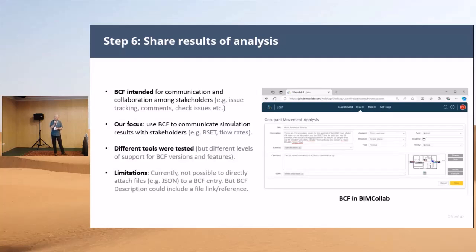We use different tools, and ultimately there were some limitations that we encountered with the BCF file format, primarily because it was originally designed as an issue tracking tool with fairly small notes and packets of data going around the design team. We wanted to associate it with larger sets of results. We wanted to know the flow rates through the doorways, for example, over time, and the performance of the building. And the BCF file doesn't really support either large sets of data or even particular fields for cross-referencing the data either.